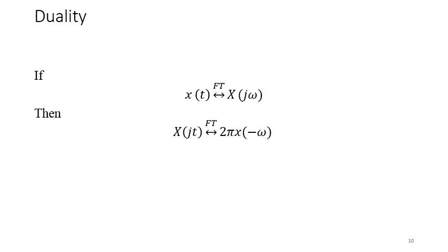We have observed symmetry, in fact consistent symmetry between the time and the frequency domain representations of the signal, right? And you understand, for example, a rectangular pulse in time domain corresponds to sinc function, or similarly a rectangular pulse in frequency domain corresponds to a sinc function in time domain. Also, a pulse in time domain corresponds to a constant signal in frequency domain, and similarly a pulse in frequency domain, if we go to the time domain, we see that it is everywhere, that is a DC signal or a constant signal.